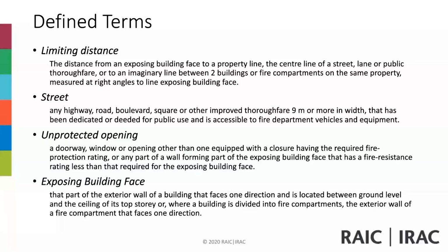If you have a wall with a fire resistance rating and it has a doorway, a window, or an opening that does not have a closure, then it does not have the required fire protection rating.